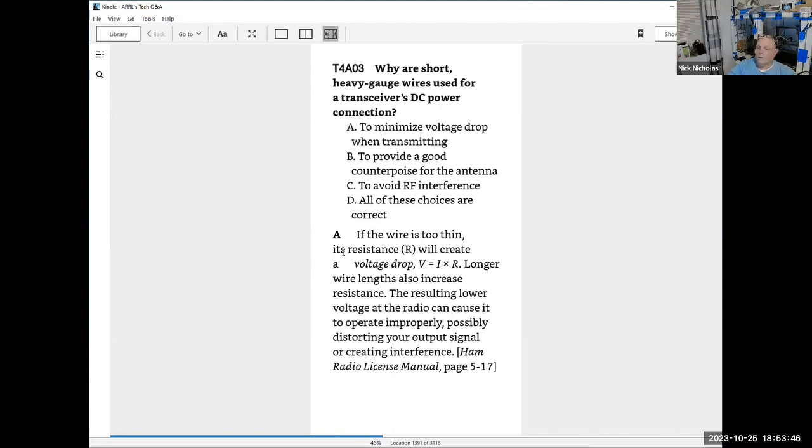That can end up being 10 or 15, 20 feet of wire. So keep that in mind. As a practical matter, you want to keep that wire as big as you can, if you can afford to get away with it, and it is practical. I mean, you're not going to run wire that's 2 inches in diameter, although you wouldn't get any voltage drop from it. The greater the diameter of the wire, the less the voltage drop, because it offers more surface area for the electrons to flow through.